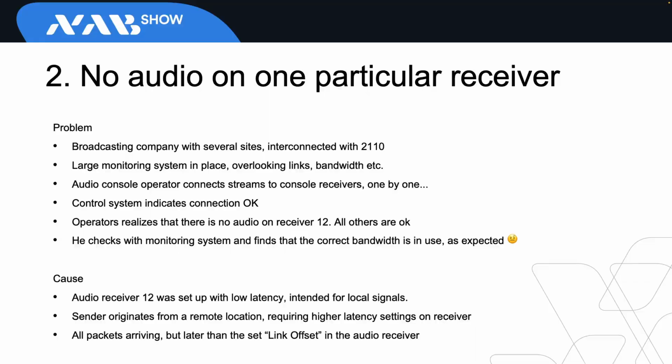He doesn't realize at that moment that the DSP for all of this is sitting somewhere else in a different building. And we all want to do distributed productions, right? So he shouldn't care about this anyway. But in audio, every millisecond counts. So this receiver was really set up for 2-3 millisecond latency, and the packets were just all late. So no system would indicate that to him until he really looks into that particular product, that manufacturer.